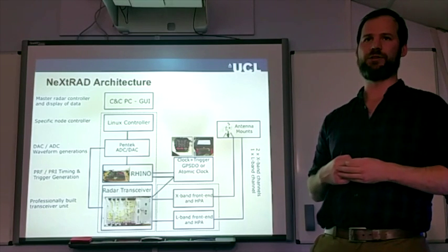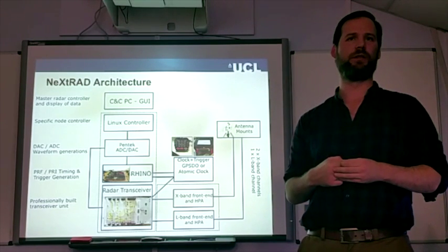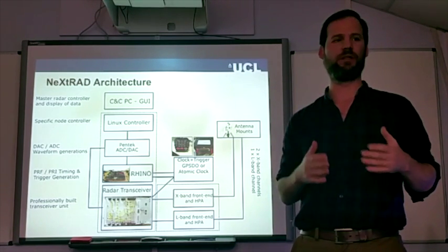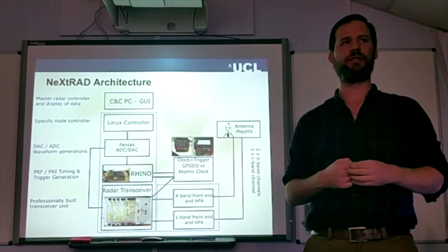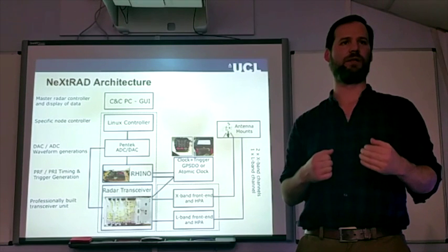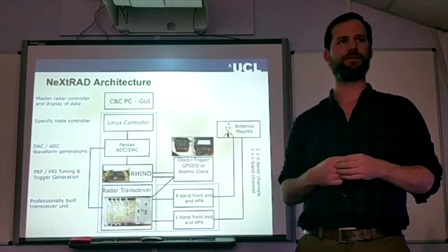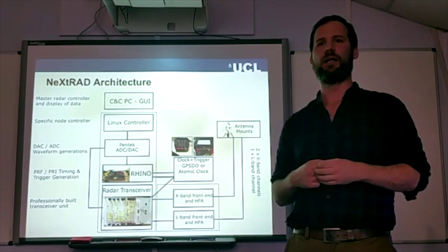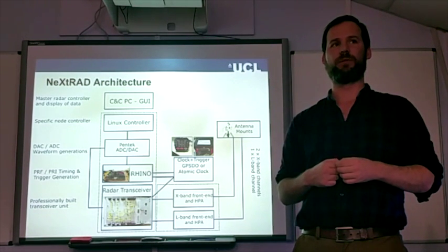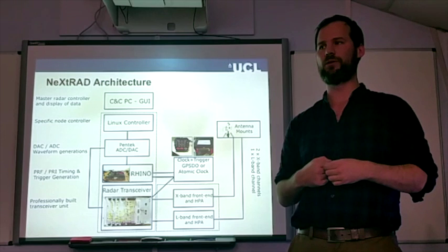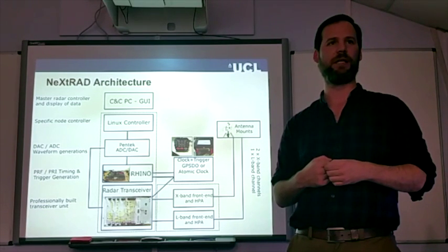As part of clocking the system, one of the key fundamental issues with multistatic systems is the synchronization. To allow you to be coherent with multiple radars, you need to receive a coherent signal, so knowing exactly when it's transmitted and maintaining phase. To do that at multiple sites wirelessly, we achieved that using GPS disciplined oscillators, with bespoke designed units from the University of Cape Town.